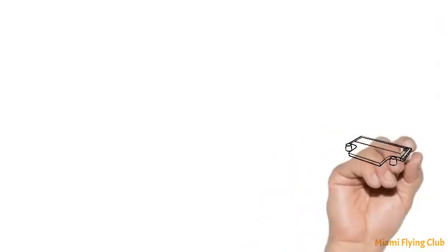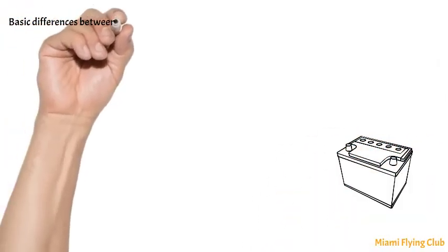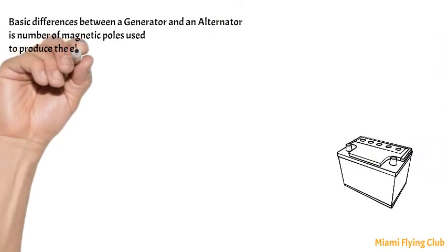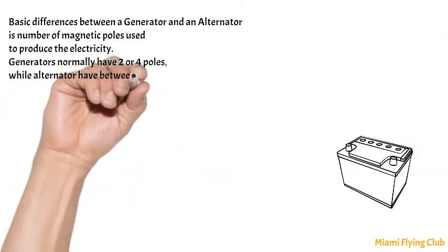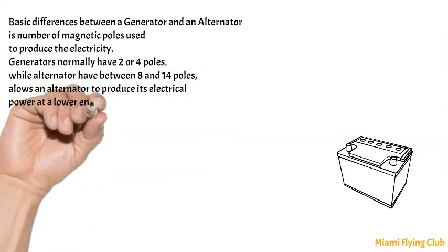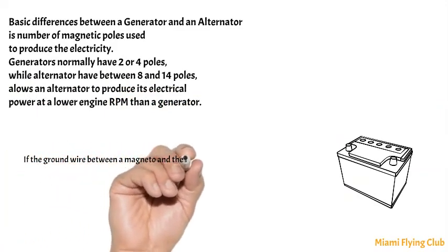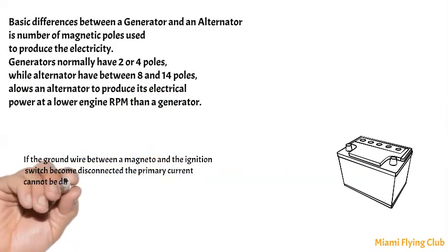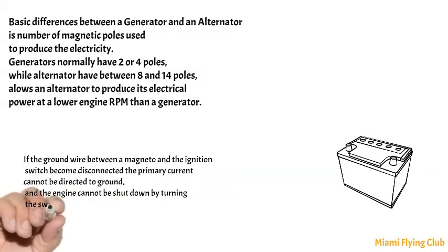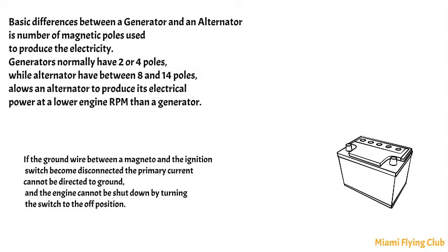Electrical system. Electrical power is provided by a battery and alternator or generator. Most aircraft use alternating current, AC, as their main source of electrical power. But because of ease of storing direct current, DC, electricity for starting the engine, almost all small airplanes use DC systems. When AC is needed for instruments, an inverter is used to change DC into AC.